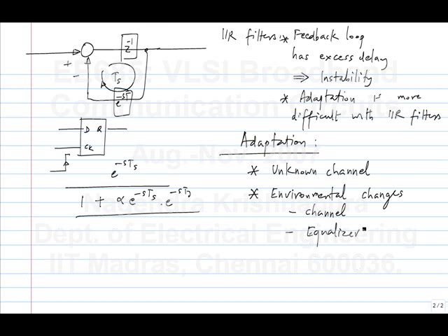What happens? Could the response change? How? Why would the response of a filter that you make on a chip change with temperature? Component values will change. The simplest thing to think of is the transistor gm, especially if you have a bipolar transistor, it is directly proportional to absolute temperature. So that will change. If you have amplifiers that have a factor of gm in them, that could change.